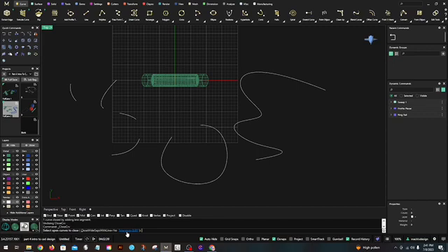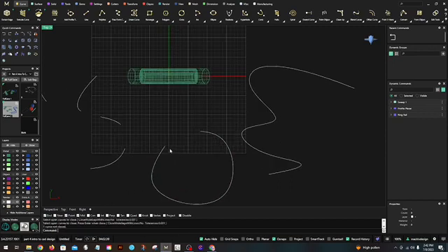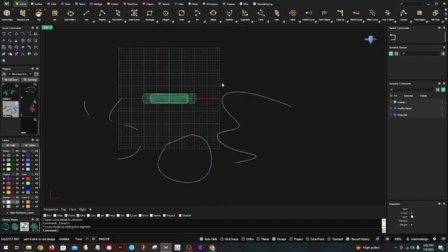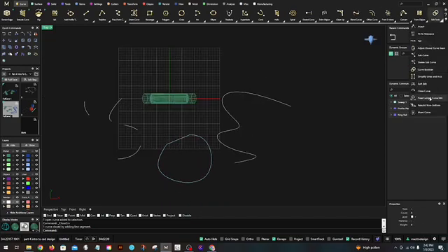And it does have a tolerance. Close wide gaps with line. Let's say no. Okay, if it does, that's the only option. So they won't close it unless they close it with a line. So I need to put yes on there. Wonder if I put like 1 millimeter instead of 0.0001. Oh, it does the same thing. Okay, well now we know how that works.